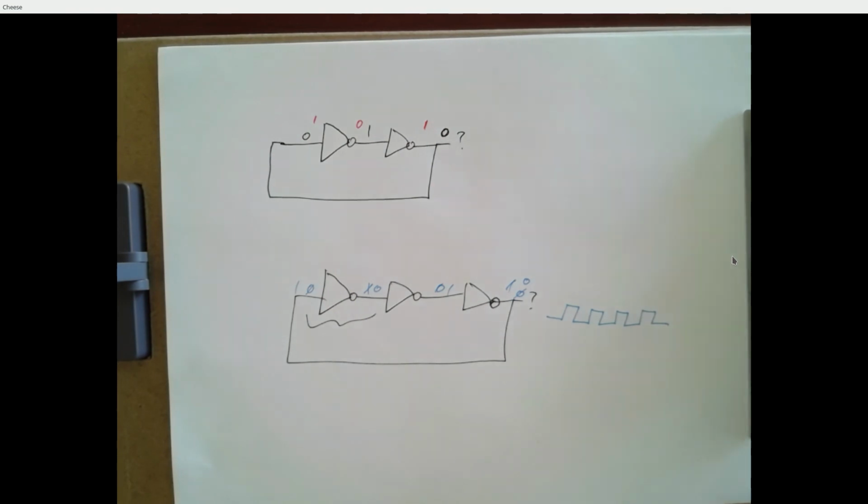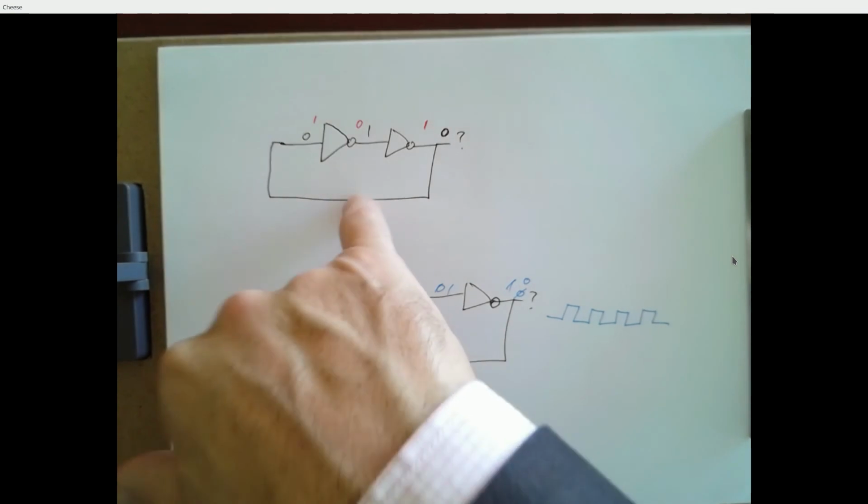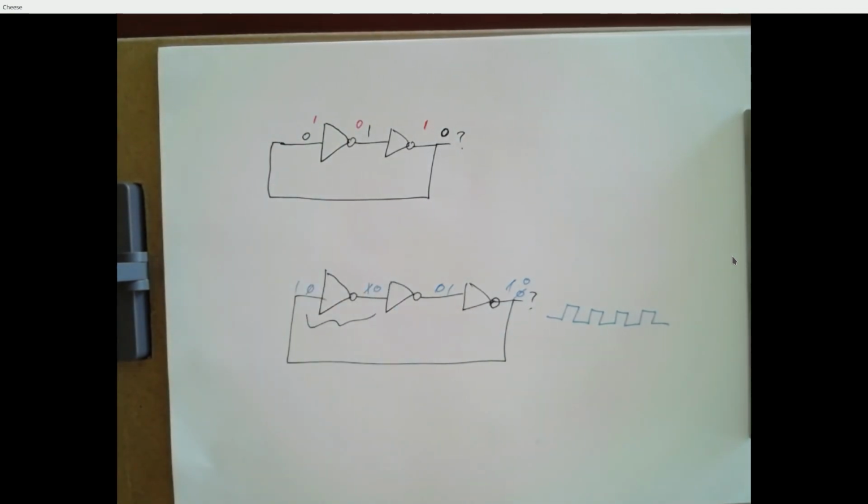Okay. Couldn't you get the same result with a capacitor? Yes. So that's the difference between static RAM and DRAM. DRAM, the cheap stuff you get for your computer, is based on capacitors. Cache memory, the really expensive stuff inside your CPU, is based on this kind of setup. So we'll come back to that.